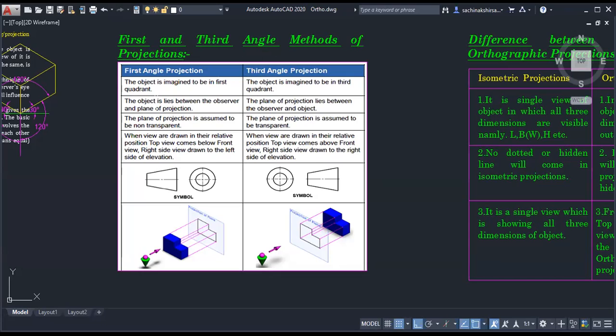On the other hand, now in this chapter, side view also we are going to draw. Side view also we have to remember. Maybe it may be LHSV, left hand side view, RHSV, right hand side view. So where will it come? Right hand side view will come towards the left and vice versa. It is there vice versa because the object is remaining in between.